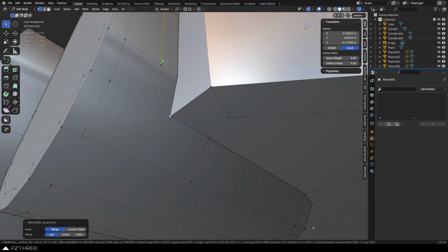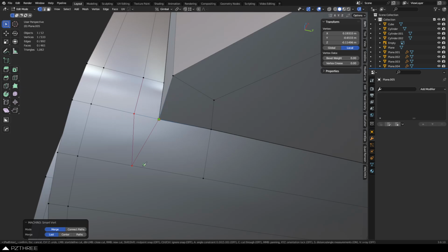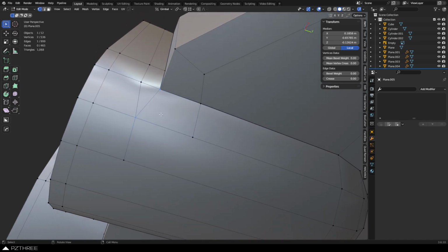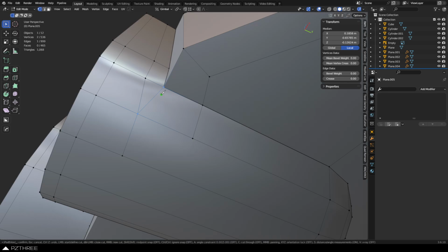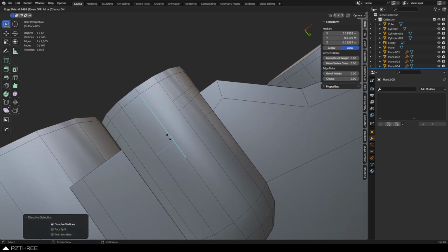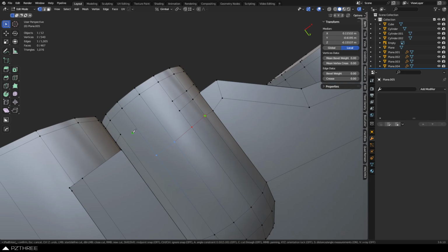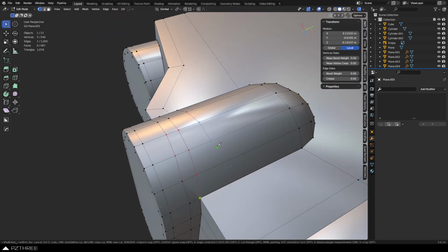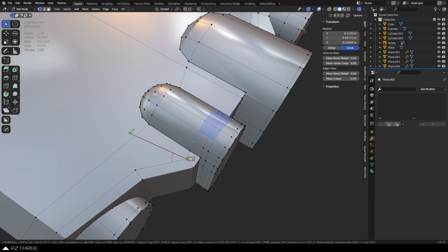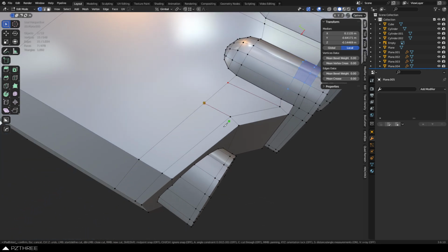And so, if we're trying to do this all the way across down to here and back there, you can see it gets a little bit squirrely, but is that even going to work out? I don't know yet, but it did create a nice little weird triangle shape. Could we just run it all the way through and do that for now? I guess. I don't know. So doing all these additional edge cuts, this is going to eat up some time, obviously. If you can avoid it, it's probably better to avoid it and just do the bare essentials. And then you can hopefully do loop cuts in later on. But you can see how these all start to work out.